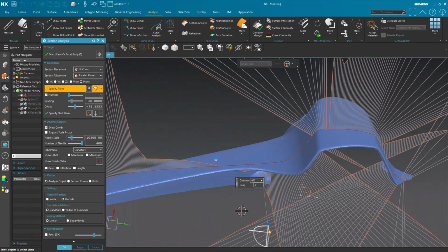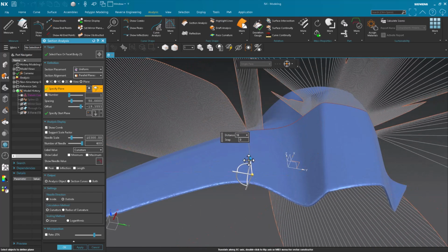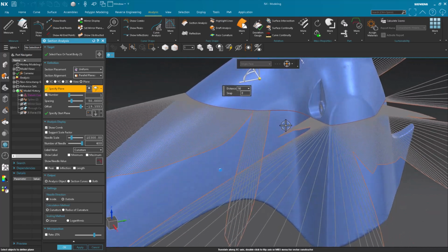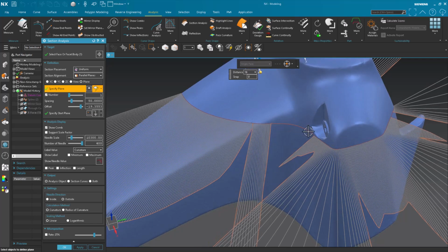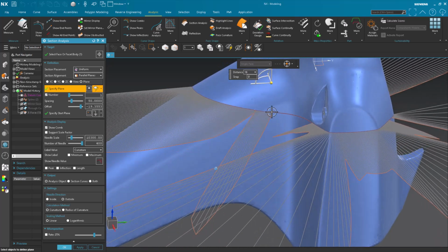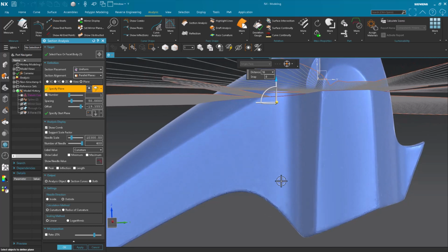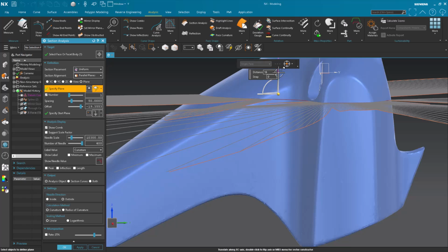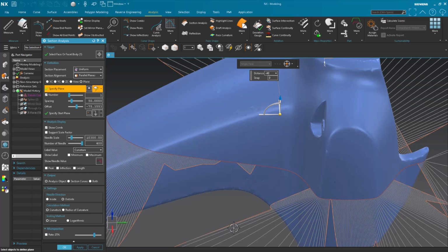Okay, chances are, judging by when I get closer to the top, you'll note as I get up here, obviously they get smaller and smaller and smaller. I have a blend in that surface, and right about here is where that blend begins and ends. And I come straight down, and you can sort of see that light running along that surface. That's where the reversal is going to happen, or the change in direction is going to happen, right along that tangency. I don't want it to happen way back here, right? That's not what I want.